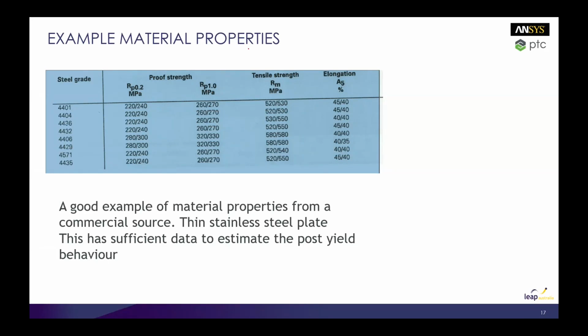With steels, they don't display a definite yield point. Sometimes there's this dip and then it goes into the plastic range. In Ansys, we consider these 2 points to be the same, so we just have a straight transition. Then we've got the percent elongation. We treat these as though they're engineering stress, which is generally what they are.